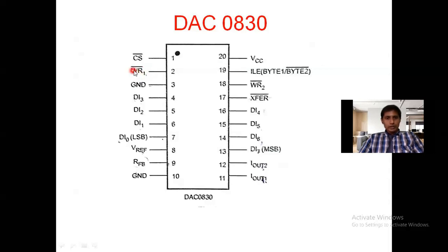There is one register called the input latch register. That register is now receiving 8-bit digital data whenever WR1 bar is activating. And who will activate WR1 bar? This WR1 bar is activated with the help of CS bar and ILE pins.